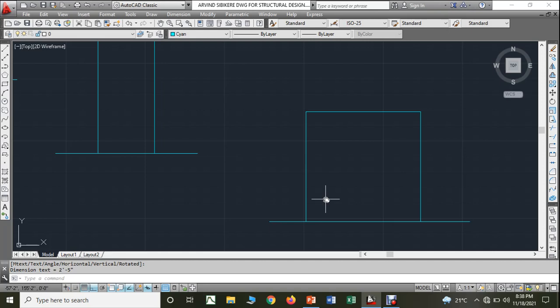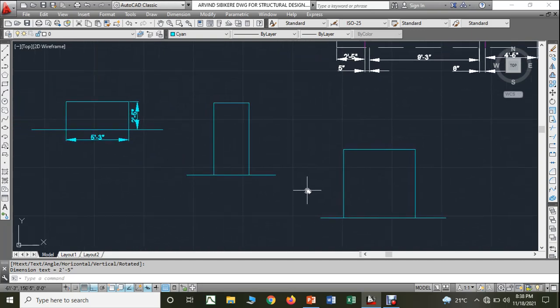However you rotate, it is not going to change. Even in the square column, however you change, it is not going to change. But changing the moment of inertia just by orienting the column is possible only in the rectangular column. Therefore, I can make the structure more and more stiff just by orienting the positions of the columns.